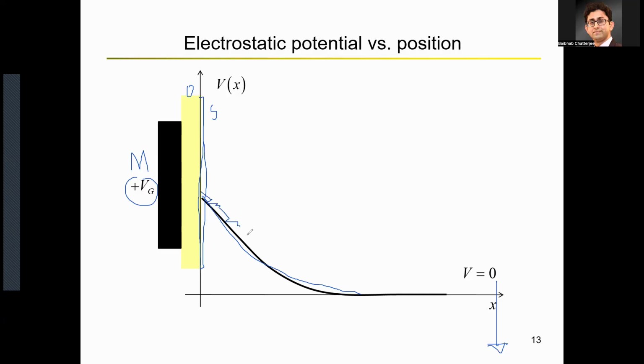After all of those large resistances, you get the ground. At every point you have a voltage drop, and gradually that drop across all these resistors increases until the total voltage drop equals VG, and at that point you reach 0 voltage. That's how the voltage profile looks inside the semiconductor.